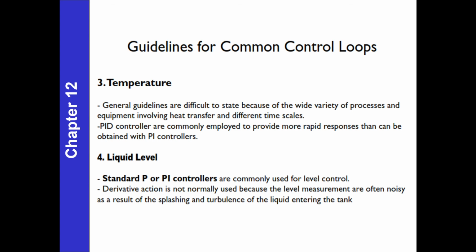In some cases, the noise is amplified more. And for the temperature, you need a D element because the temperature is a very slow process. And for the liquid level, you will just need P, or you can use PI if you want a more accurate response. But if you can tolerate the offset, you can use P only. I think that's all; my topic has been covered.